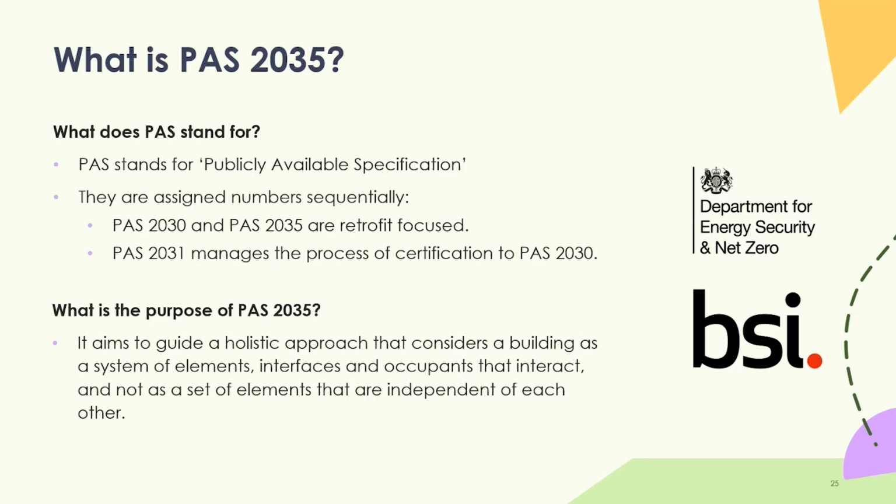It's a standard that covers when you should install, when you should commission, how you would plan for this, assess things, evaluate, all the rest of it. PAS 2030 is quite specifically about the actual on-site installation of stuff. So that's more for your installers, to be PAS 2030 accredited, showing that they can install technical things to that standard. It's kind of like a Russian doll, nested within PAS 2035. You do your PAS 2035 process, you get to the PAS 2030 bit, and you carry on with PAS 2035.